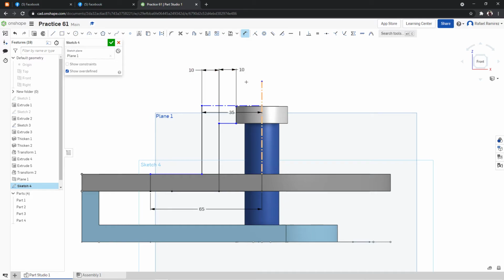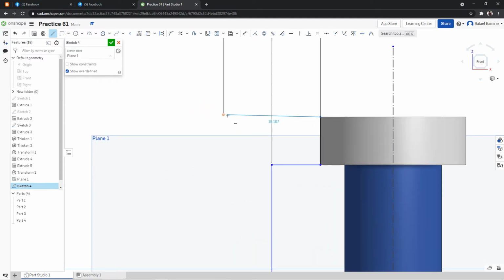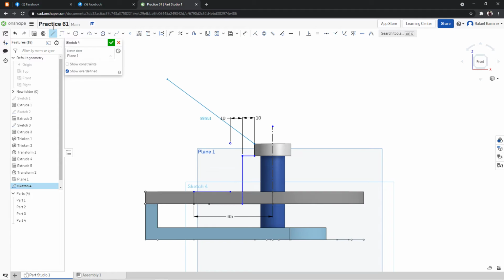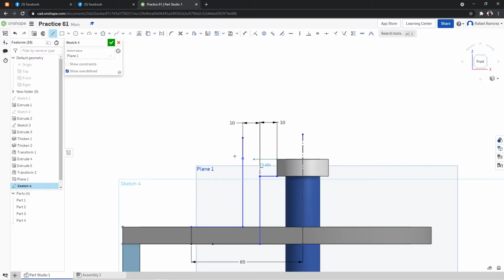And then, that's about it. Then I'm gonna cut this one, since I need to have actual lines, not construction lines, for me to be able to use the extrude tool, because I cannot use an extrude tool using construction lines. I mean, yeah, we cut the excess lines.